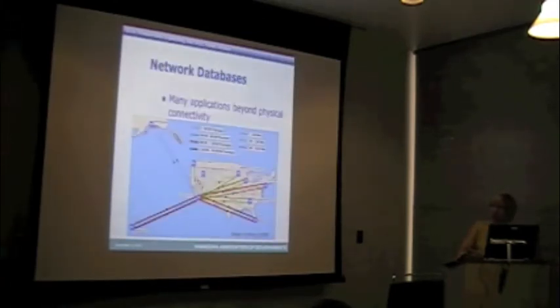So the alternative way to structure networks is the link and node system. If the linear reference is so great, then why do we even care to have links and nodes? Links and nodes pretty much fragment the network way too much. Now, the purpose of having a link and node structure is if we're going to use software that's going to run network graph traversal algorithms. Anytime we want to model connectivity, we have to have a node and link structure.